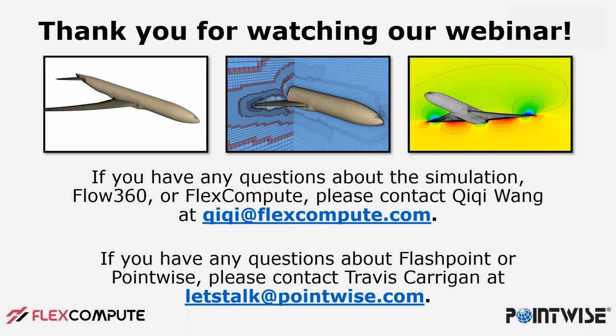If you make changes to the setup for Flashpoint surface meshing, or you come up with any local resolution filters, you can save all of that off to a Pointwise environment file, load that up, load in a new geometry, and again, push the button on the toolbar and it'll automatically apply all of those same things. So if you're making geometry changes, just push the button on the toolbar and it'll remesh using the exact same setup that was used to mesh the baseline case.